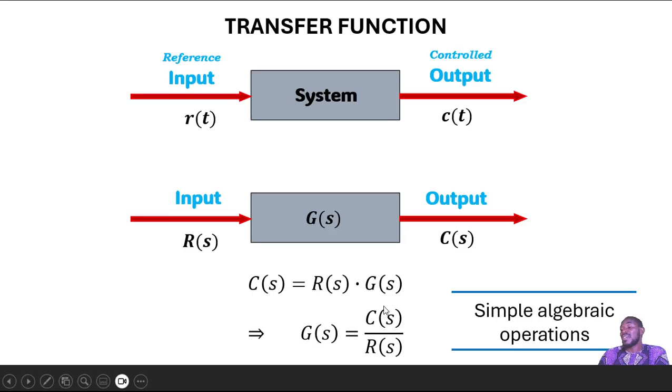Now, this is an open loop system. When we looked at the types of systems, we looked at one of the classifications where you could classify control systems as either open loop or closed loop systems. This is an open loop system because nothing of the output is being fed back to the input to check whether the desired input is being achieved. The input just comes in, the system works on it, and whatever output comes out, you take it, whether you like it or not. It's an open control system: input, system, output. This is a transfer function for that.